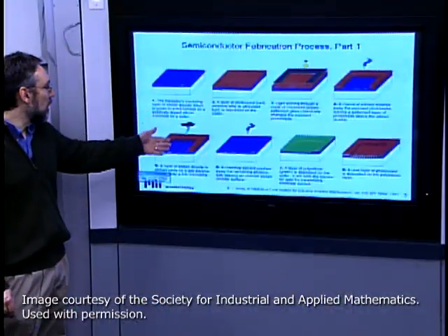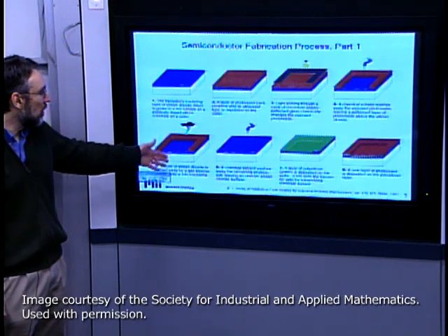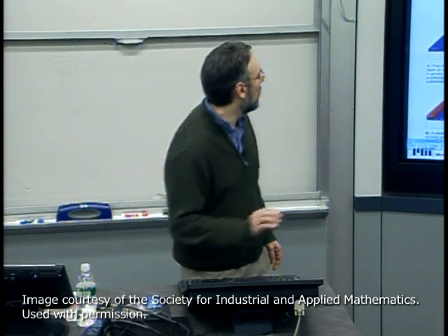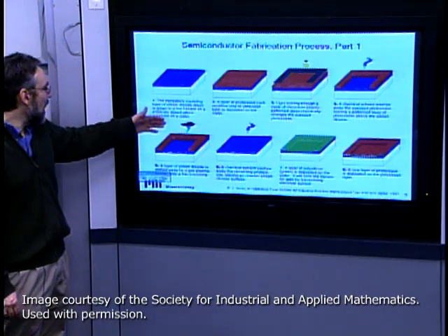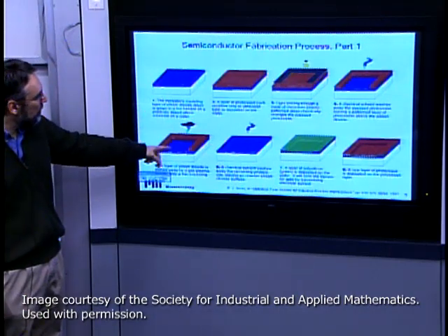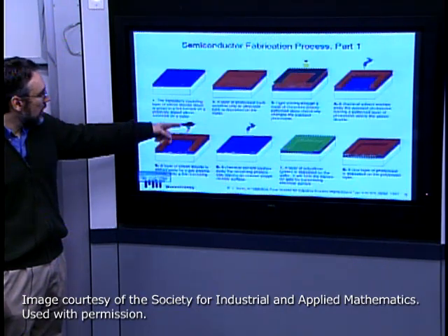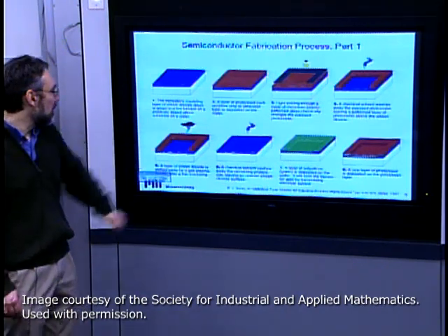Its purpose is to act as a mask to allow us to differentiate more aggressive physical transformations of the remaining wafer, and in particular in the following case, as shown here in step 5, this is saying what we want to do now is do another etch of the silicon dioxide layer. In this case, using a gas plasma etch. I guess that's what the little lightning storm here is.